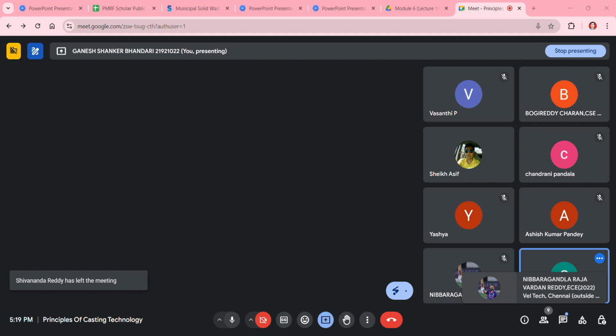So in one trip, 23 divided by 6 into 0.67, I think. And the collection vehicle compaction ratio is also there, 2. So your total volume will increase from 23 meter cube to 2 times, so that will be 46 meter cube. You can fill that inside the container, and you have to divide it by 6 into 0.67.